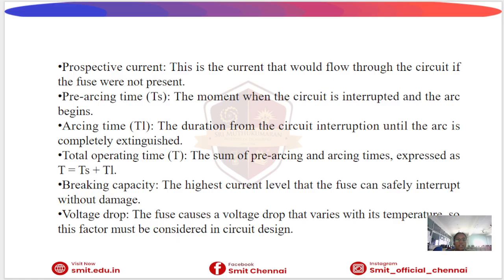Next, pre-arcing time: time taken for the fuse element to start melting. Next, arcing time: time taken to extinguish the arc after melting begins. Total operating time: the sum of pre-arcing and arcing times expresses the total operating time. That means T is equal to Ts plus Ta. Next, breaking capacity: the maximum current the fuse can safely interrupt. Voltage drop: the fuse causes a voltage drop that varies with its temperature, so this factor must be considered in circuit design.